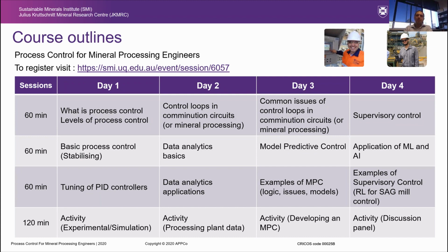And that's what I've found over these past few years actually is going to deliver a lot of value. Essentially, you're designing sensors, which is a model. It's not a physical sensor, which uses the input from different sensors currently installed in the processing plant, and tries to infer parameters that are very hard to measure, or that you cannot measure reliably. And that could be a good input.